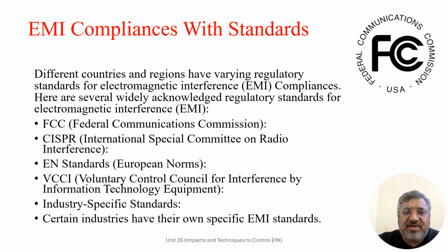VCCI, which stands for Voluntary Control Council for Interference by Information Technology Equipment, is a regulatory body in Japan that establishes standards for EMI compliance for information technology equipment. VCCI regulates specific limits for conducted and radiated emissions based on CISPR standards and requires compliance testing for products